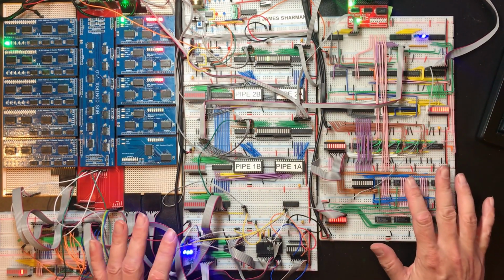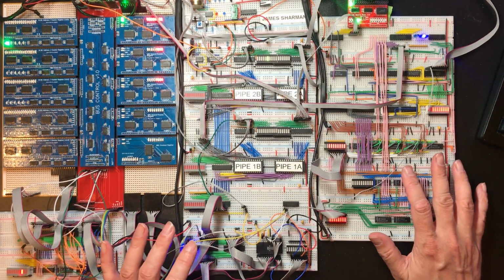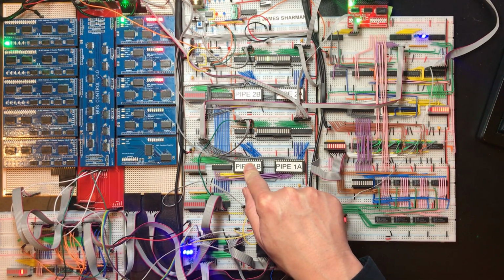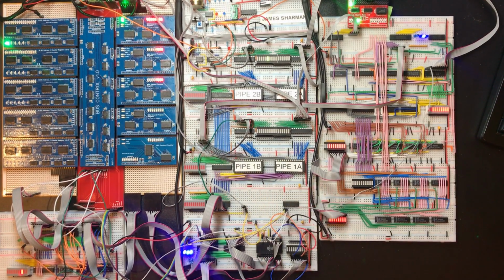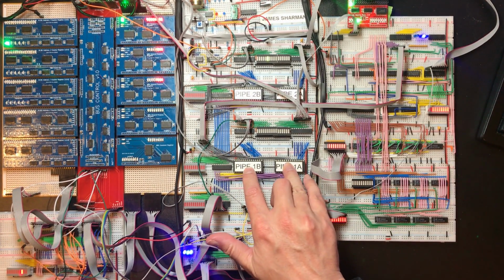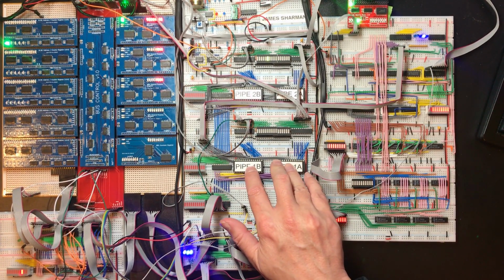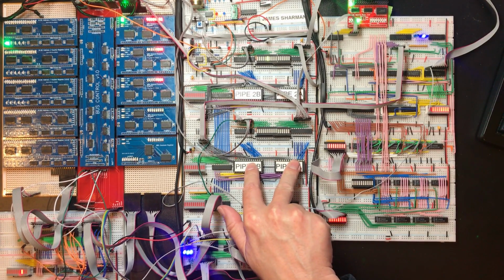Okay, so inevitably we're going to spend quite a lot of time in the software side of things. Each of the pipeline stages can now examine the value of the flags. We're going to have to update the code that generates the control ROMs in order to make use of the flags, and we're going to need to add some instructions. But let's just remind ourselves of a couple of things.